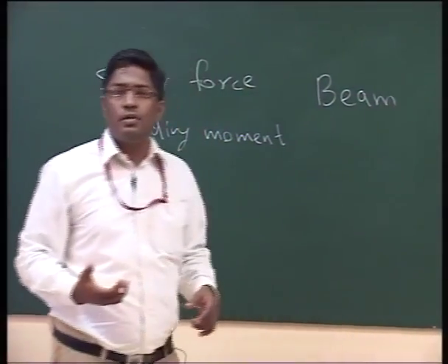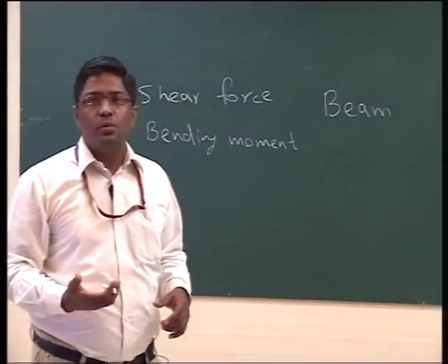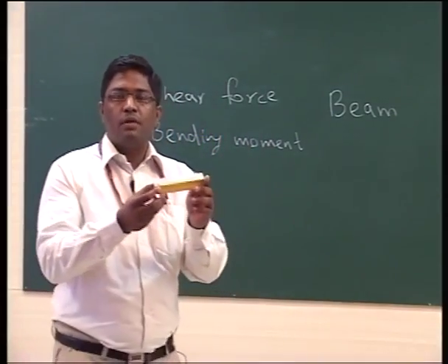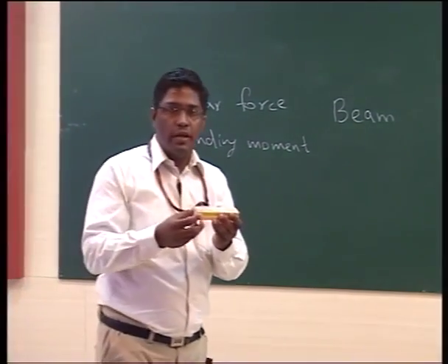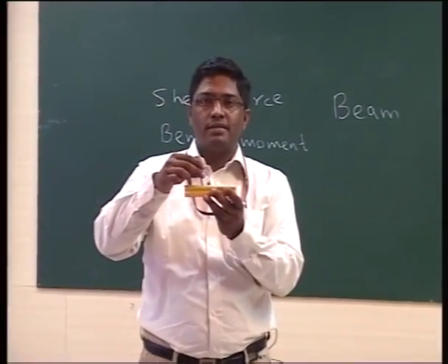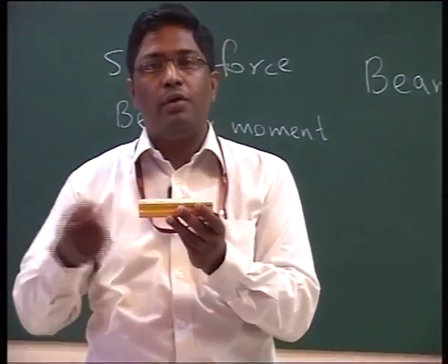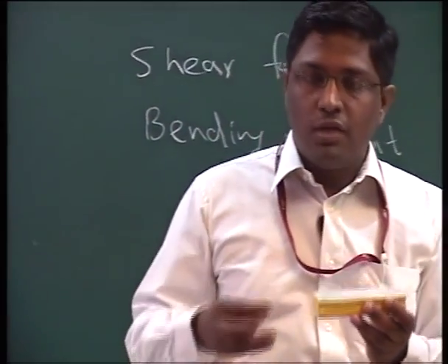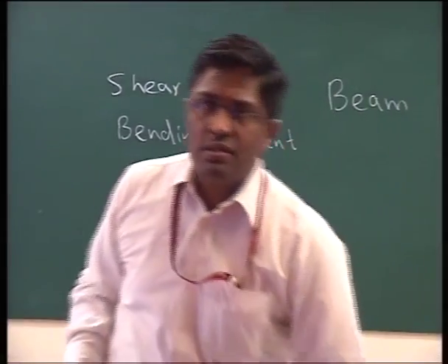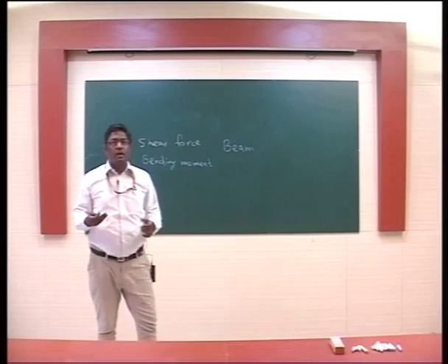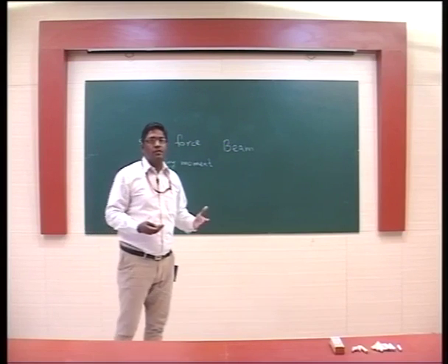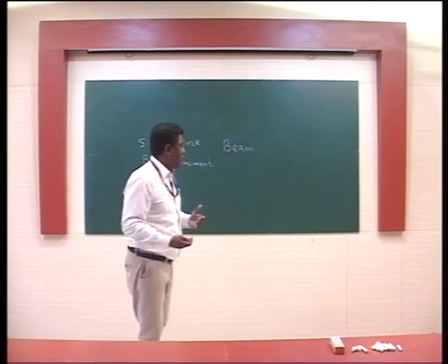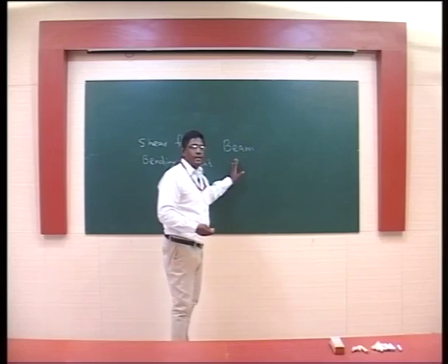A beam is a horizontal member which is subjected to transverse loading. Transverse loading means if we see that this particular thing is a beam, then transverse loading means the loading which is applied like this on the axis of this, whereas longitudinal loading means if we apply the load like this, it will be called as longitudinal loading. But in the civil structures, like the beams which we see in our houses or our structures, it is always a transverse loading which is applied on it as point load or UDL, which I will tell you later. So this is called as beam.